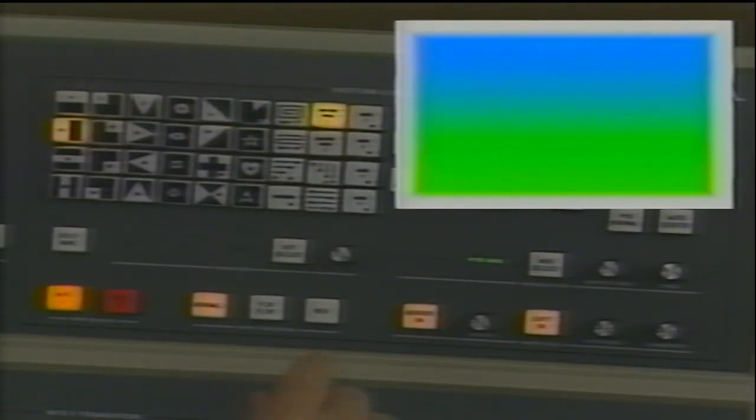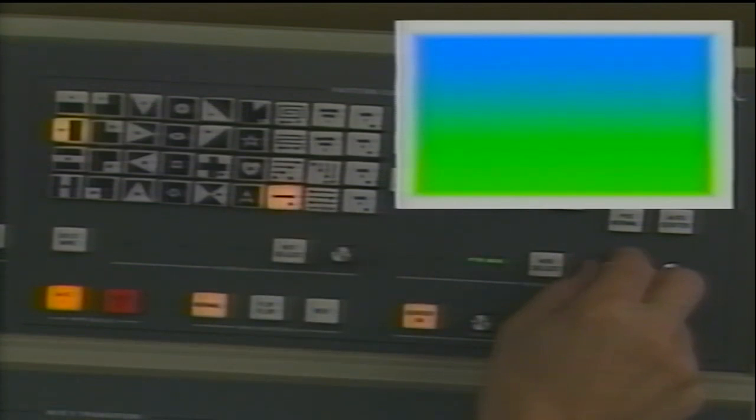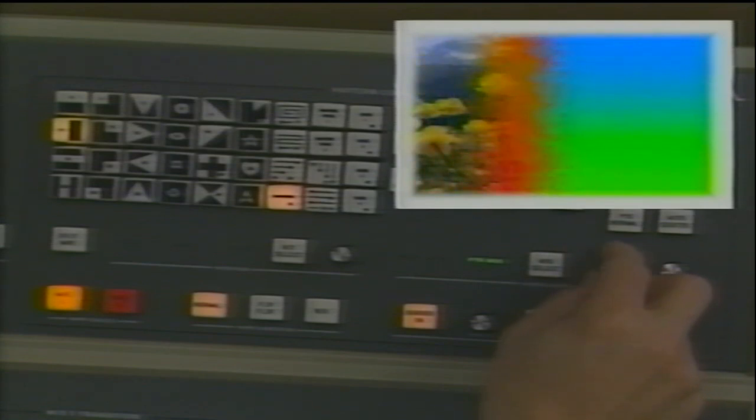A special feature of matrix wipes is pattern mix. The Modulation Select push button is used to choose pattern mix. Pattern mix allows the user to combine any analog pattern with a matrix pattern and is only active when the matrix wipe option is installed. In this case, curtain and the random pattern have been selected. The modulation amplitude control now becomes a pattern mix control, which determines the ratio between the two patterns.